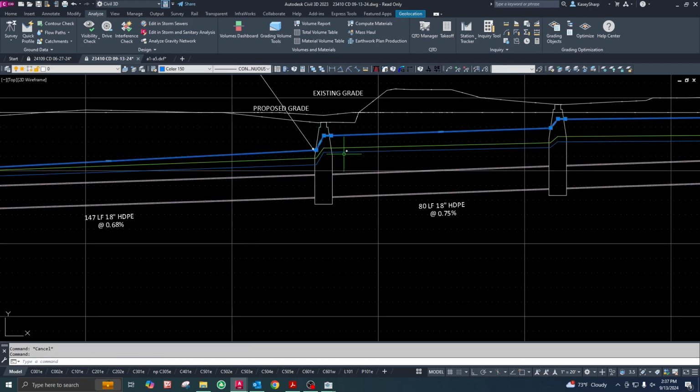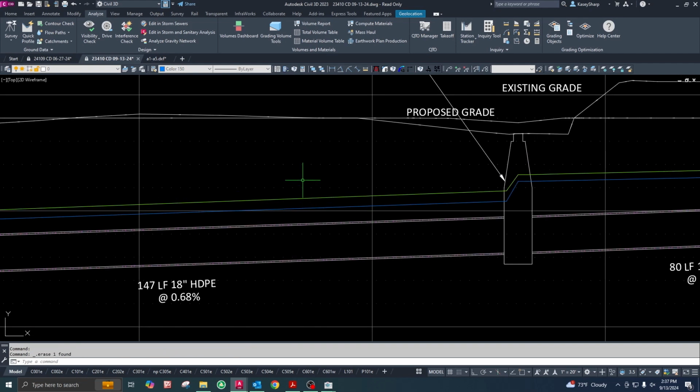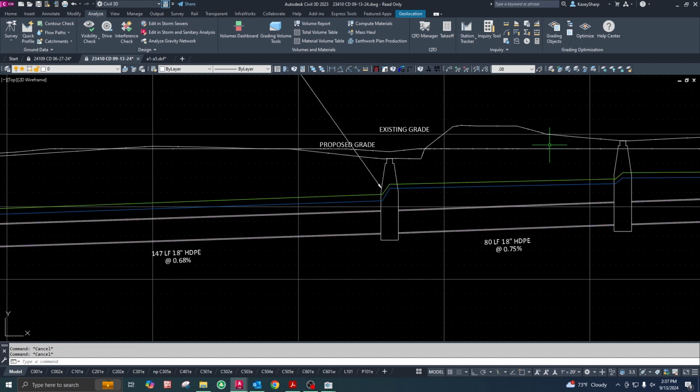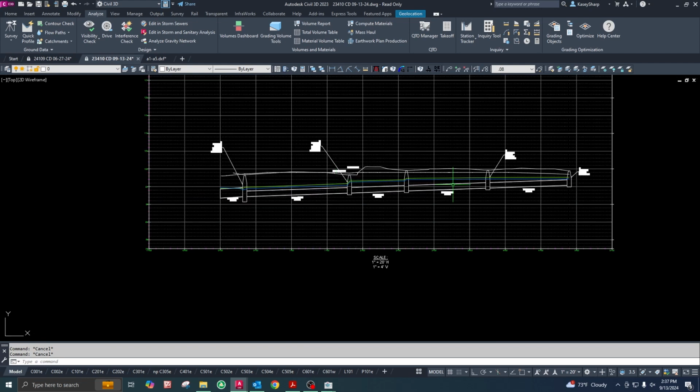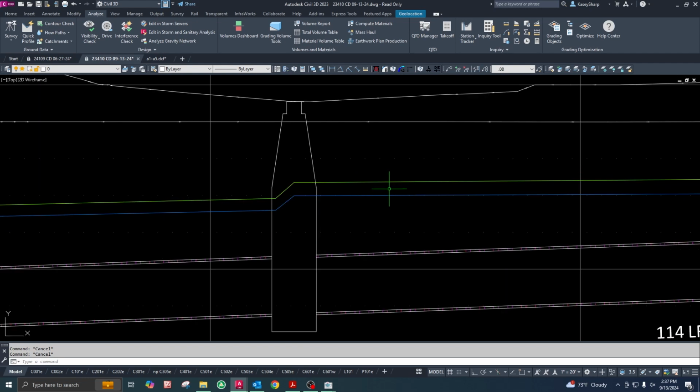I specifically picked these two colors for all the HGLs that I show on the profiles because they're thin line types, but also very dark. Typically, a lot of the times when you generate HGLs, the lines will be super close to each other. That's just how it works out. They're index colors 70 and 150.